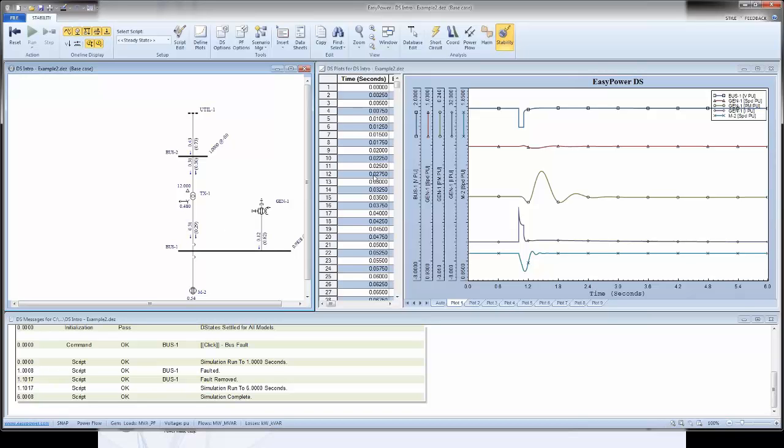Dynamic stability is going to plot all these curves for you, and if you have protection devices in your system, they will also act, and they will also trip, if there is a case that they should trip. So imagine now you have a combination of short circuit on your system. You have your devices that are going to operate based on a precise behavior of your waveform, and those waveforms are not going to look like a square waveform. They're going to look like the real waveform with transient values, as long as you define the proper models here, and on top of that you get a log here.